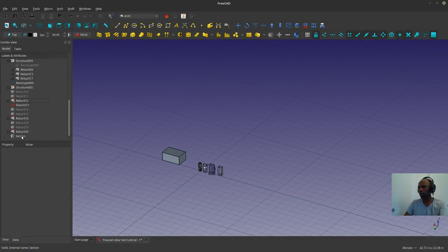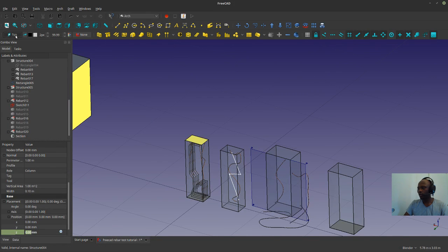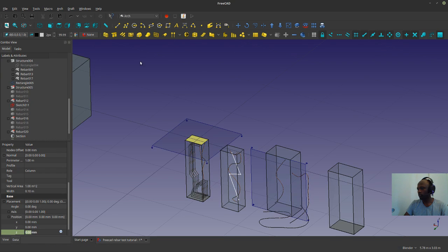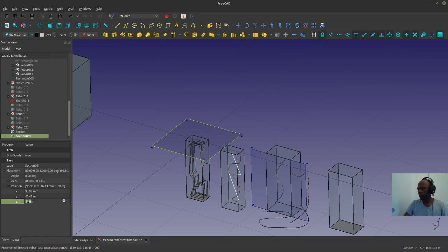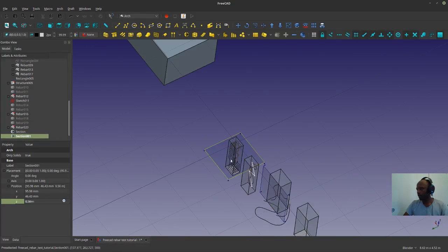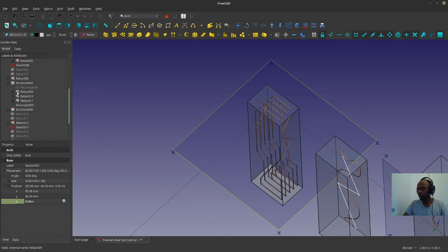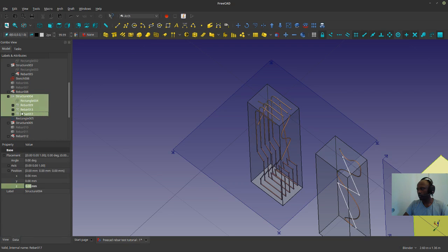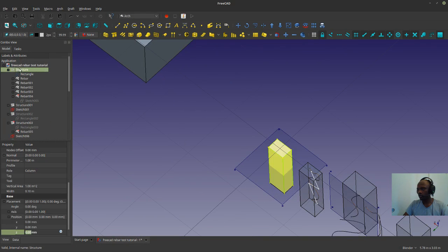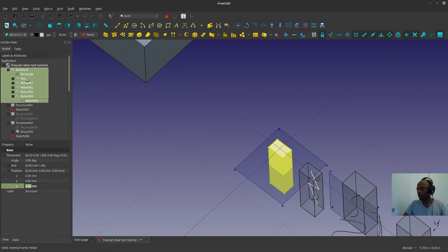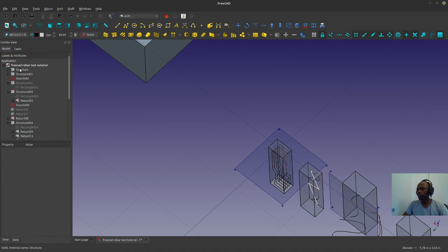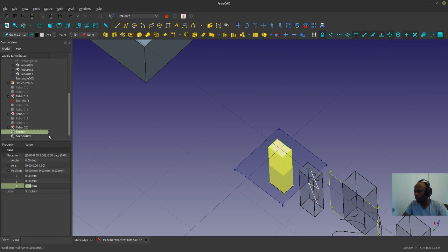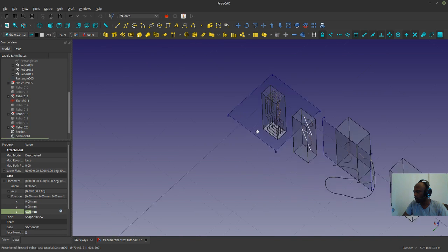Whoa. What happened to my section? Bring that back and add a section. 0.5 m. Okay. So in that structure, I'll select everyone. No, this structure. No, so what I'm going to do is I'm first going to select just the structure and tell it to come inside this section, add. So now click here and generate the section.